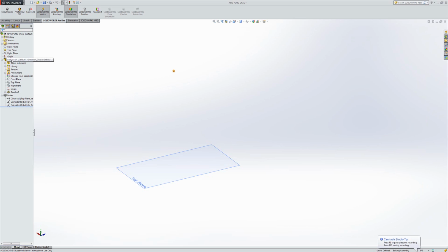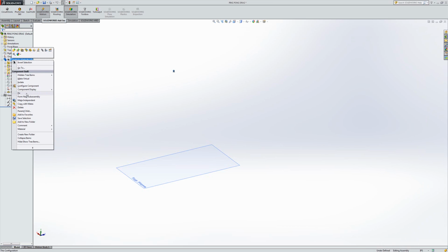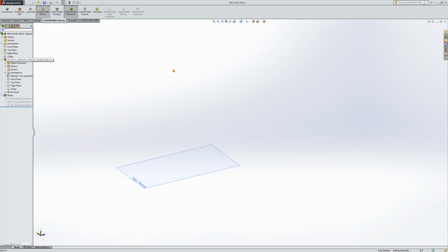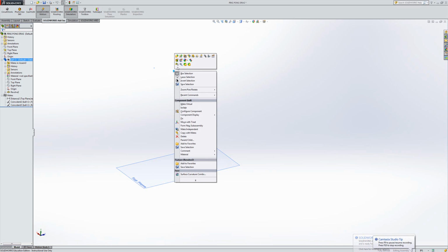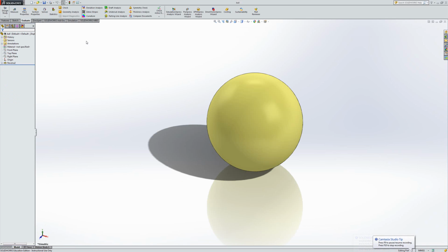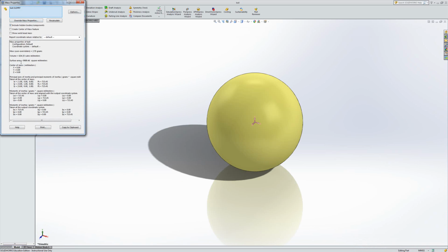Here's a SolidWorks assembly with a ball inserted into the assembly. Make sure the ball is set to floating and not fixed. You'll need to verify that the mass of the ball is correct. I'll open the part file. Yep, the mass is overridden to be 2.7 grams.